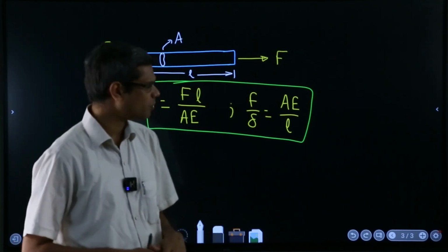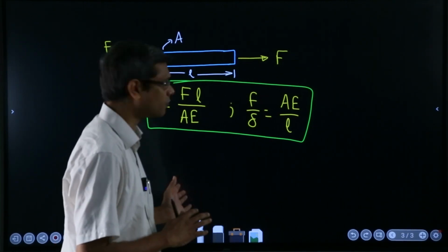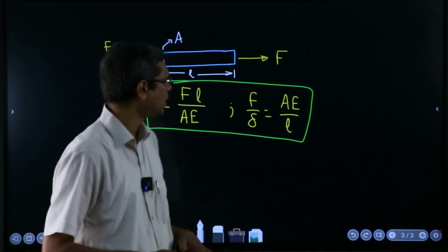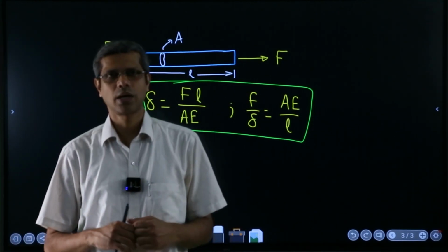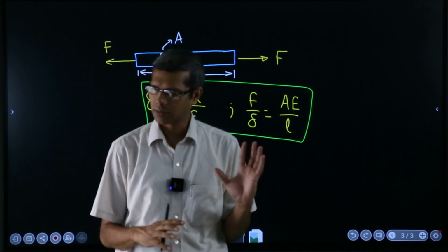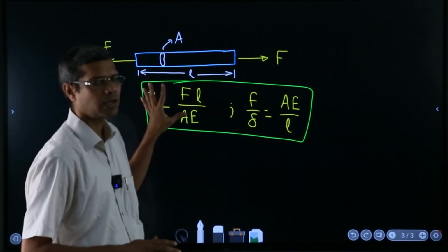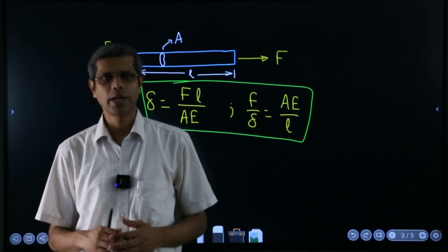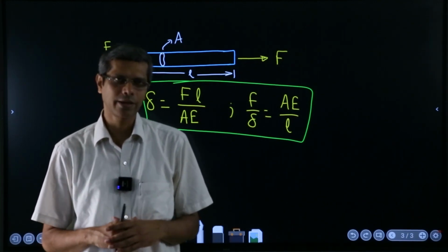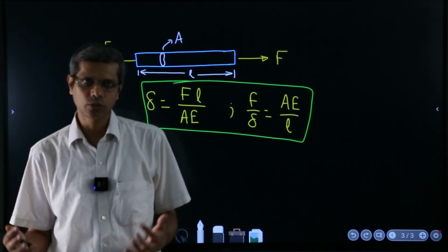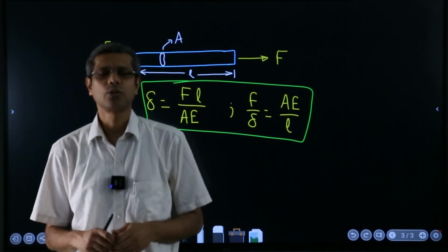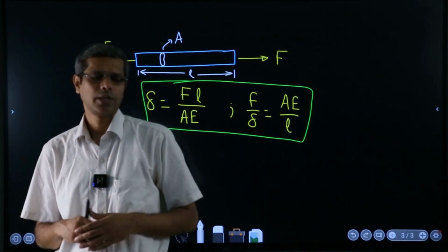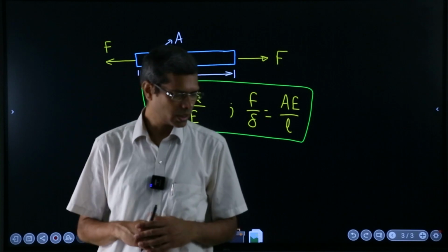We will see such problems. In this segment we defined what the axial loading condition is, what the assumptions involved are, and the material property characteristics required for this discussion to be valid. This is the canonical configuration which we will always use in situations where more complex conditions arise, and we will have to break those problems into these canonical segments, so that we can apply the formulas we have derived to those small segments. Okay, see you in the next segment with some more discussion on this.